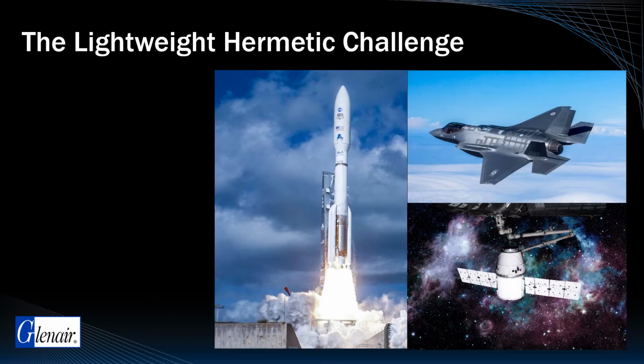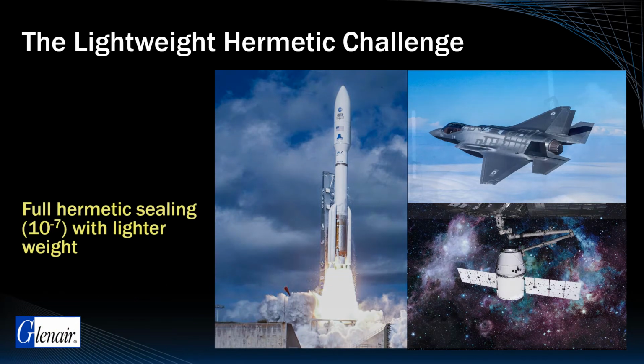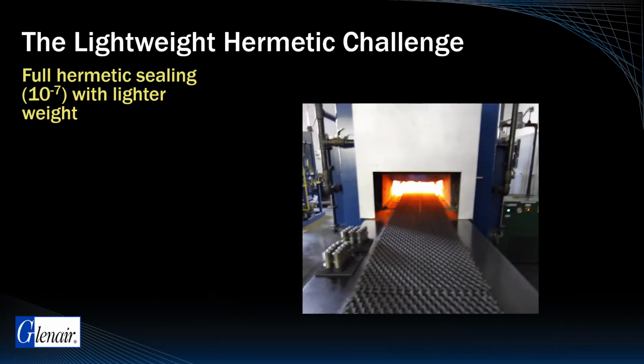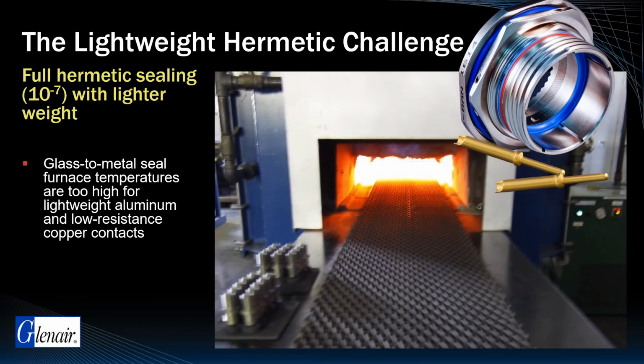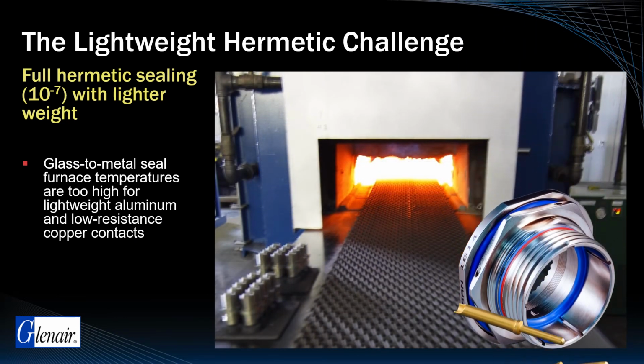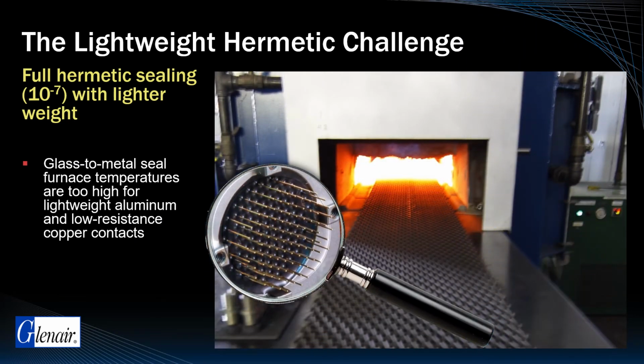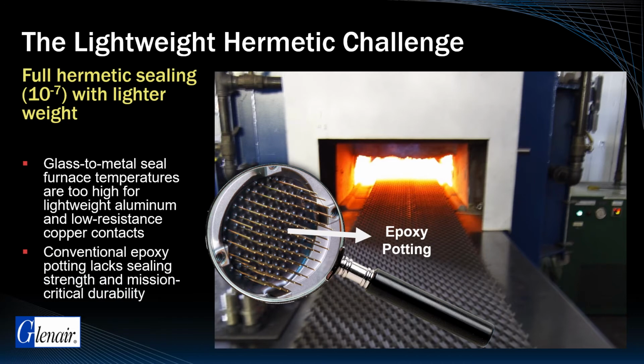The interest in a lighter weight solution is also significant, particularly for air and space applications. Unfortunately, glass-to-metal seal furnace temperatures are far too extreme for lightweight aluminum shells and low-resistance copper contacts. Historically, manufacturers have attempted to use epoxy potting compounds as a replacement process for glass, but conventional epoxy sealing absolutely lacks the sealing strength and mission-critical durability that is the benchmark of all mil-spec connector standards.